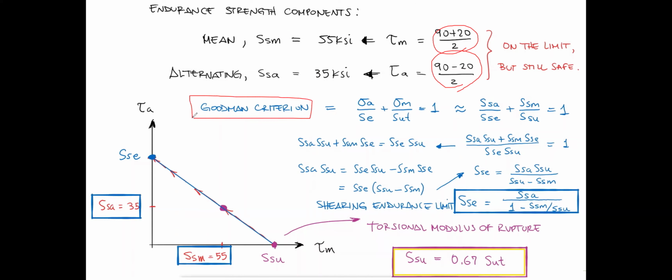it's a linear function. So for this fatigue criteria that we already learned last semester, we just use the sigma A or SA or the SN. But now it's the shear stress, since this spring is subjected to shear stress.